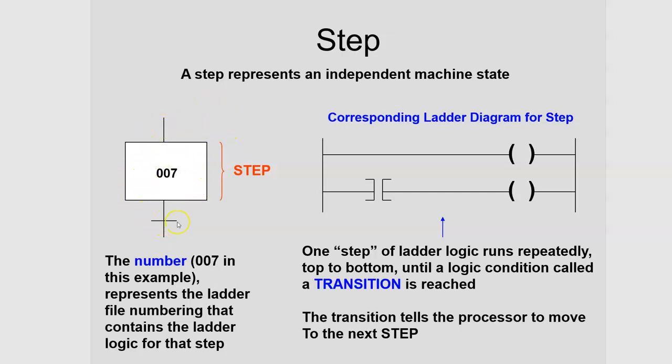So imagine this symbol in front of you. When you click on it, it opens up a window, and you're able to put a small program using ladder logic in the box. This line right here represents a transition. If you double click on that, it opens up a window where you can put code using ladder logic, the symbols that we've shown you in other PowerPoints.